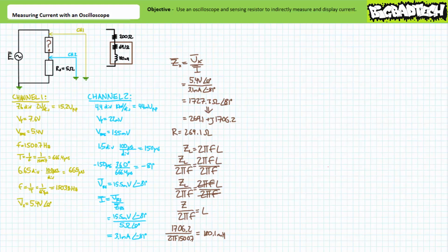While I did progressively lead you through the steps by your nose, note I never asked you to perform a calculation we haven't done so already. That's the point. We really only added one new technique to our repertoire, notably using a sensing resistor and an oscilloscope to indirectly measure current through an unknown element. Everything else necessitated your prior understanding of Ohm's law, phasor representation, complex impedance, and basic sinusoidal properties, techniques we've already discussed at some length. Be honest. Did you understand everything we discussed?